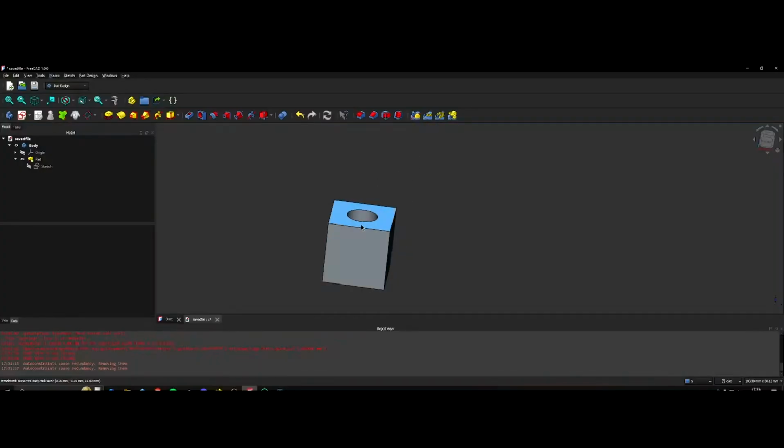The part design workbench is where most of the magic happens. It's what turns your sketches into 3D objects, and it allows you to further refine existing objects without creating another sketch. As we discussed earlier, the pad tool is what you use to extrude sketches. However, both pads and pockets can take place on already existing geometry. Let's return to our cube with a hole in it.